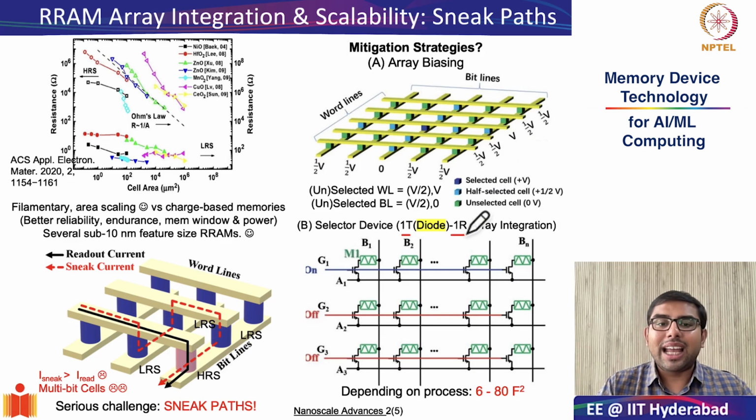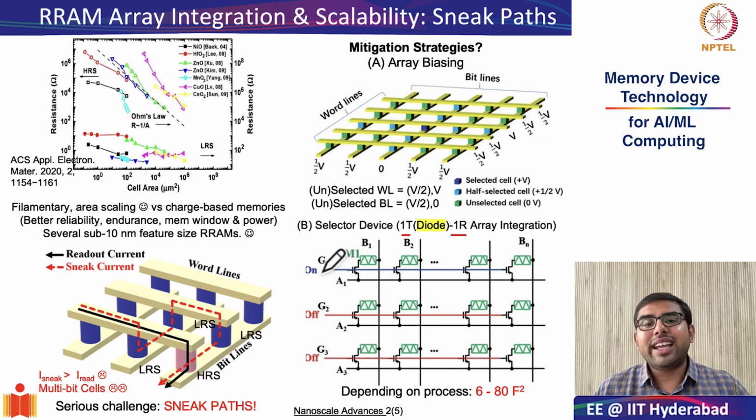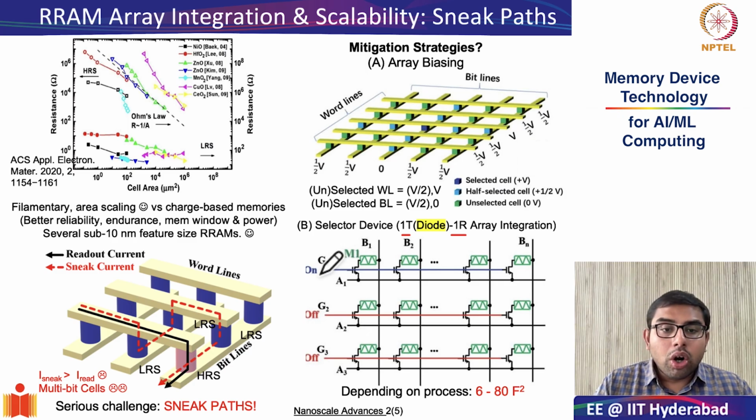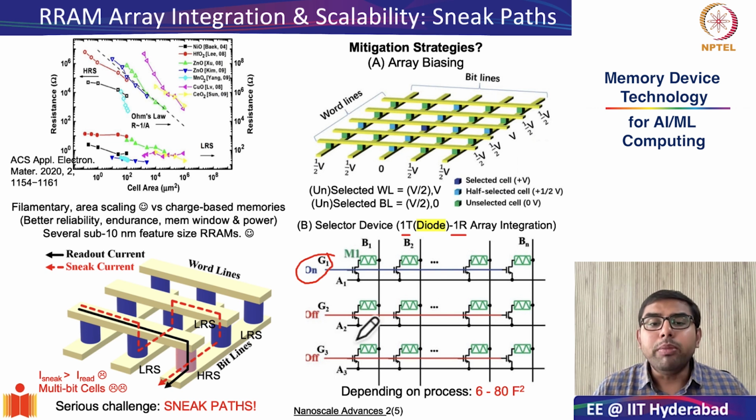So how does this help in reducing the sneak paths? This is done because just like in a 1T, 1C DRAM array, only the row which has the word line turned on is active. All other things become inactive. Therefore, the leakage through all other word lines becomes nullified.